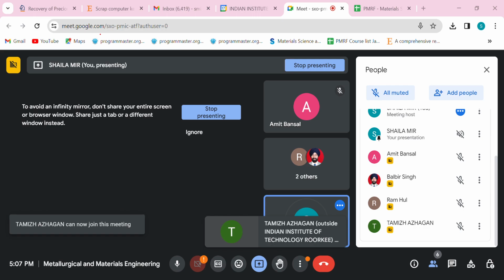Then we have magnetic particle test. They can also be helpful for measuring subsurface cracks, because if you have a crack like this and you have a magnetic material, then that magnetic material can show some magnetism because of these subsurface cracks. Also, the magnetic particles will have their own north and south poles, and they can be detected because these are micron sized subsurface cracks. So magnetic particle test can also be utilized.